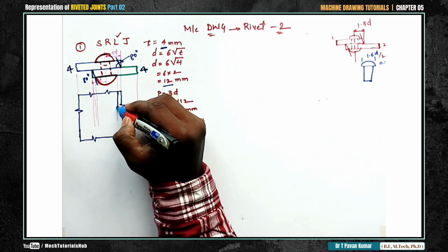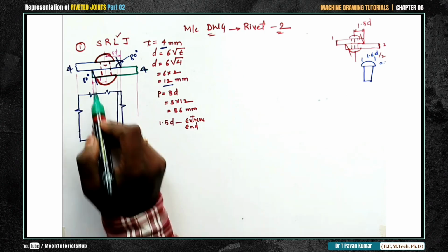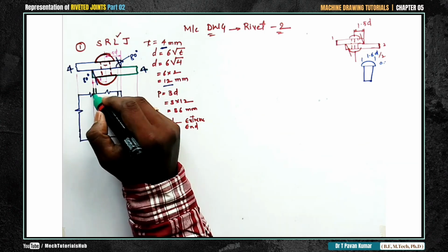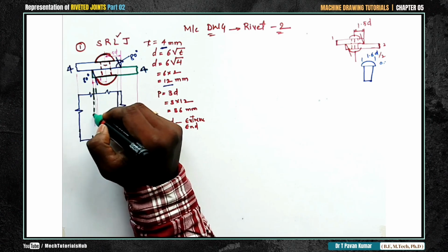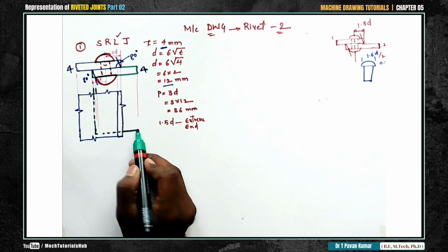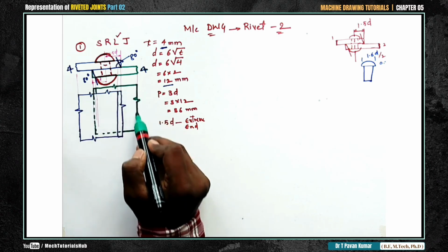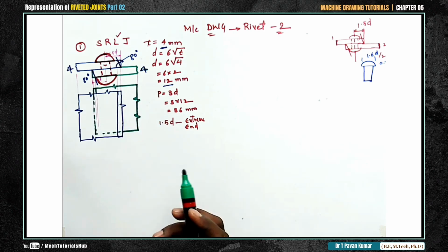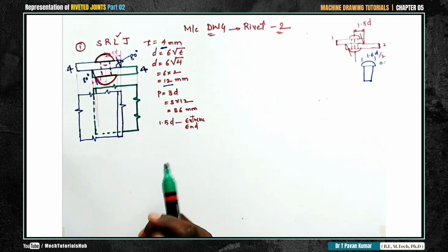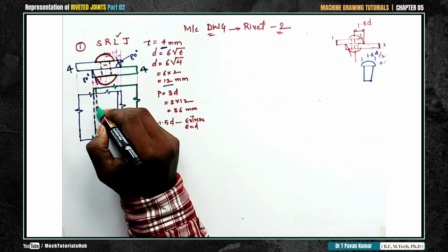Similarly sheet number 2. I'll start with sheet number 2 now. For your understanding, I'll change the color. It starts somewhere here. Whichever line comes inside, I'll make invisible. Again invisible, again darken it. From here darken it, make a zigzag, darken it. Draw one or two zigzags, that is enough. It is not compulsory to place one or two. It all depends. One more hidden line needs to be placed.